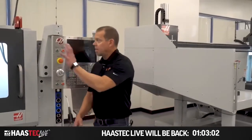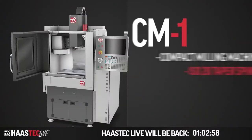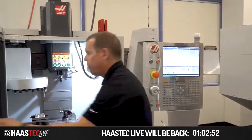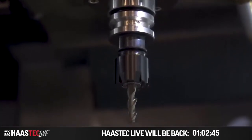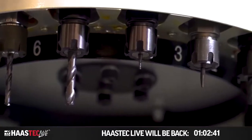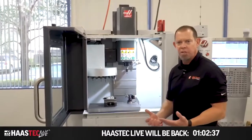All right, now we're at the CM1. CM stands for compact mill, and you can see why. Small little machine. This is an ISO 20 spindle, 30,000 RPM standard with a 50,000 RPM optional. So obviously when you have small tools, you need that higher RPM. This machine has it. Automatic tool changer, and this is primarily medical, dental, aerospace, somebody doing some prototyping.